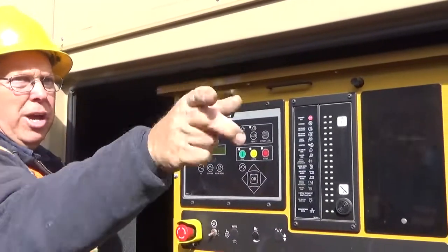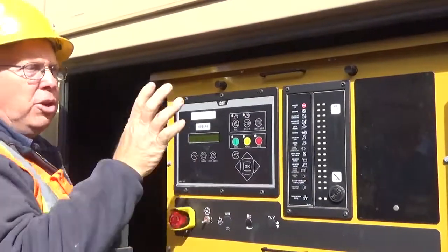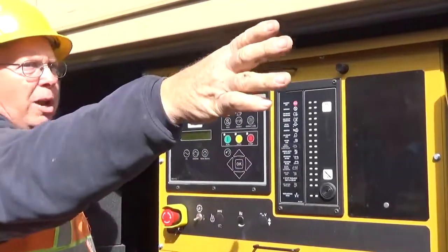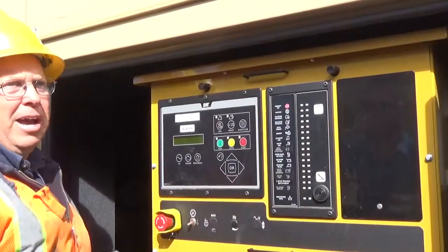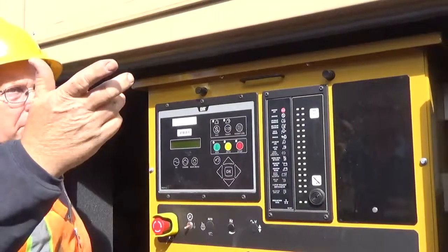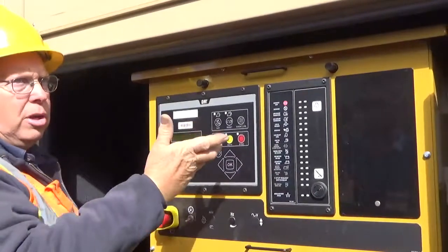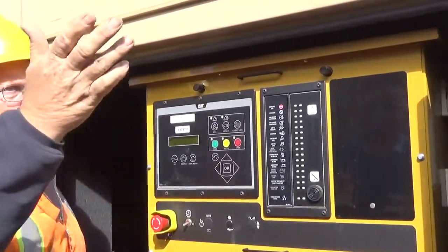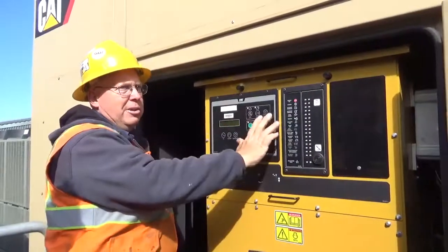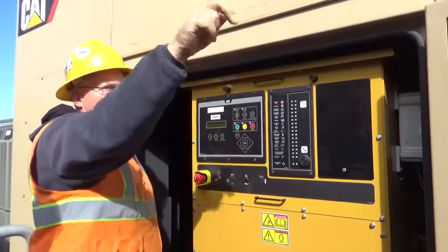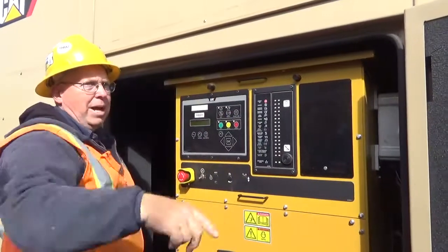Otherwise, you get this, and it goes back and forth. Because if you don't clear it here first, and you try to put it in auto, we send a signal right back to him that says, I got a shutdown condition. You can't clear him until you clear this. So you go to off reset over him, you come over here, off reset, clear your condition, back to auto, and then you go back to him.